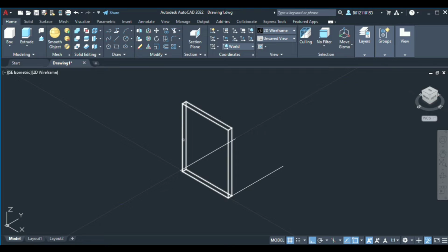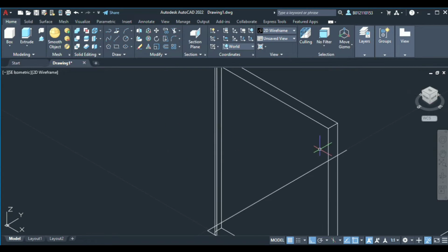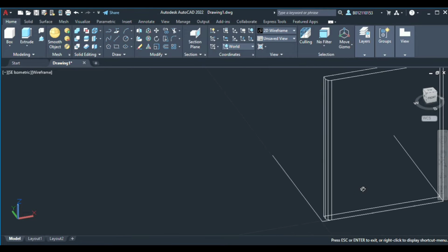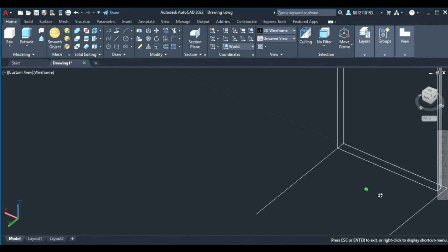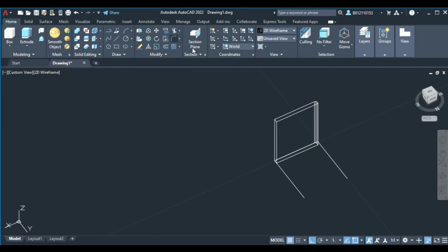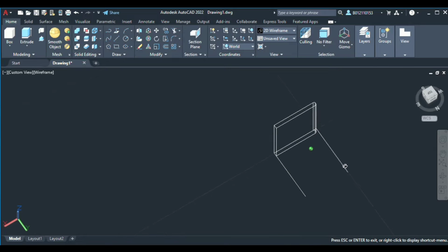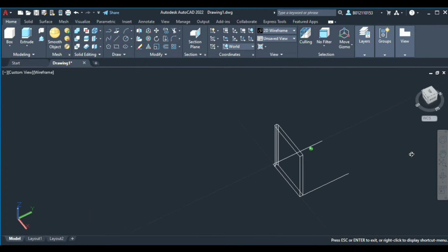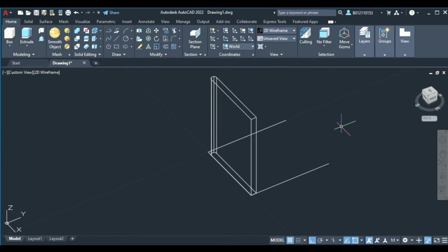We tap on this edge and then press 0.1, the radius of our fillet, and then press enter, enter again, and then the shape will be like here. We need to do it for both corners. So I will use this corner also 0.1, and then we will have this kind of shape. So we can move to the array.